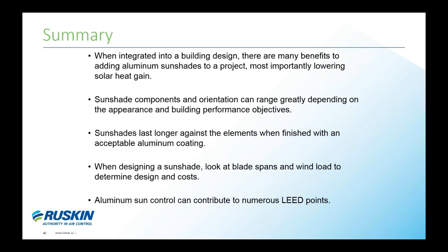When designing a sunshade, take into account your blade spans and wind load requirements, and also snow loads. A certain blade type may be required, but after looking at the wind load information, it may be smarter for cost to go with a stronger blade style. And also, using sun control products can lead to numerous United States Green Building Council LEED points.